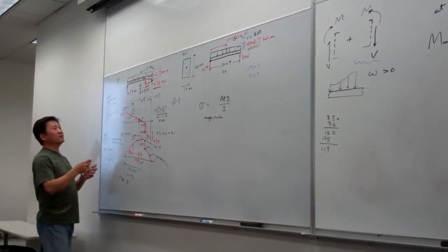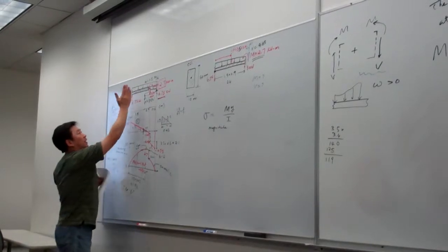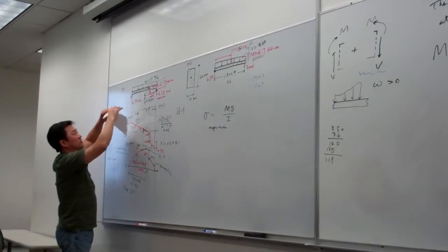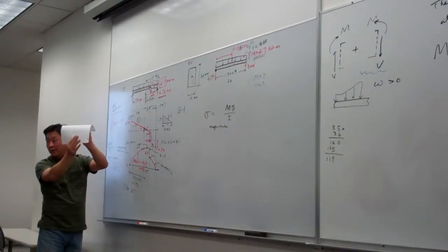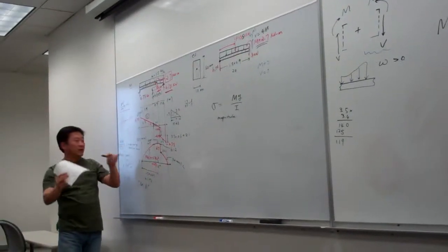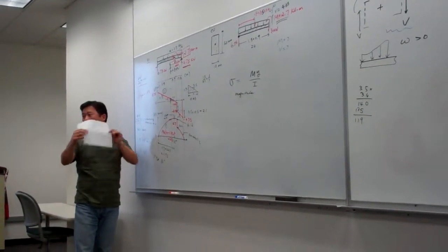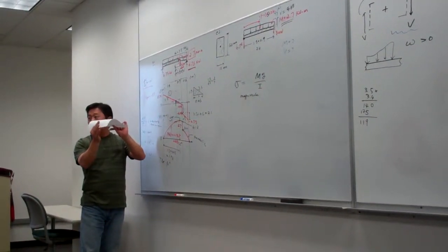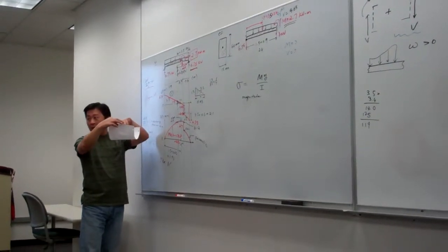Why? Because for this case, you can see the bending actually is not uniform anymore, but on every single cross section, the bending is to bend the beam like this. Not uniform anymore, not pure bending anymore, because you can see the value of the bending is changing. But it still has a tendency like this or like this. The positive M means bent up, right?